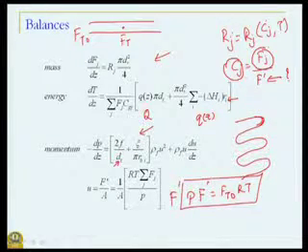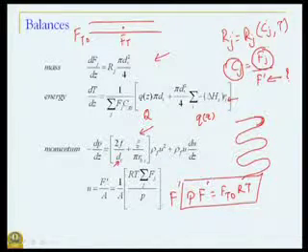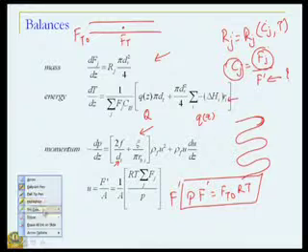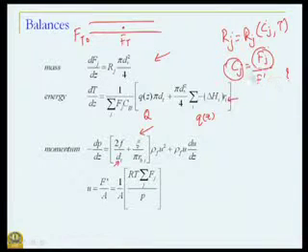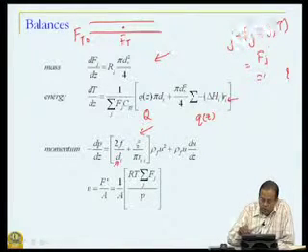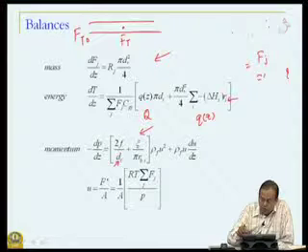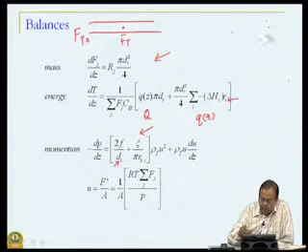So, now my F prime is R T summation F_j, which is F_T0 divided by the pressure P, and now this forms my complete model. But it is interesting to see how different things are related to each other, and we will just look at the coupling between mass, momentum and energy balance.